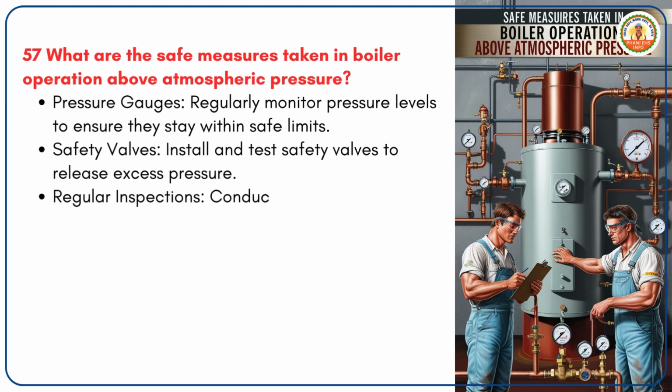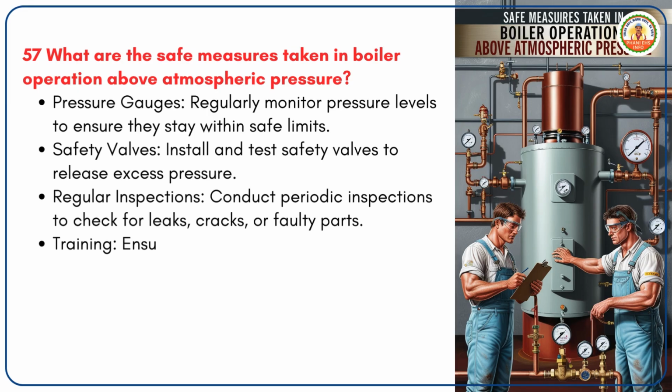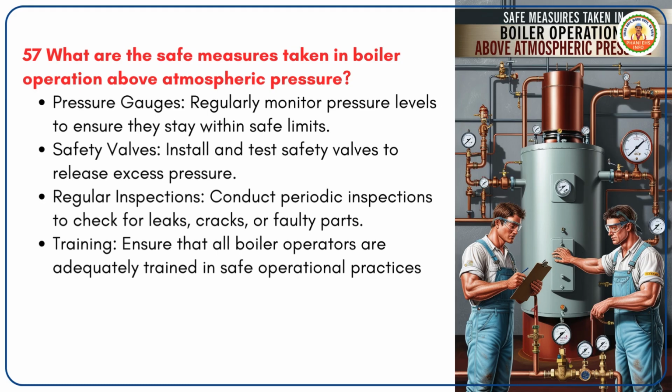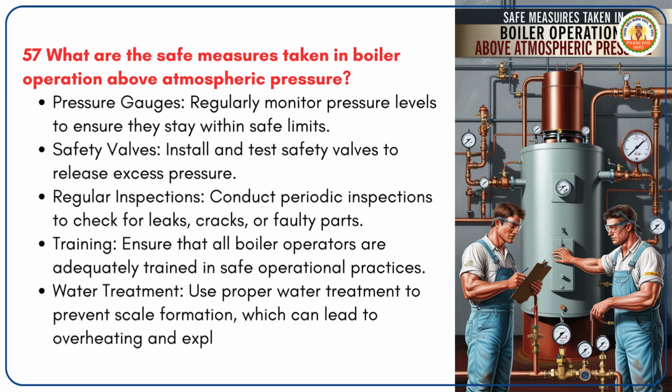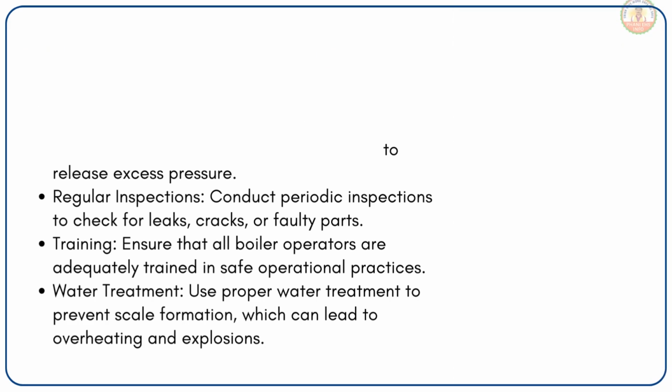Regular inspections. Conduct periodic inspections to check for leaks, cracks, or faulty parts. Training. Ensure that all boiler operators are adequately trained in safe operational practices. Water treatment. Use proper water treatment to prevent scale formation, which can lead to overheating and explosions.